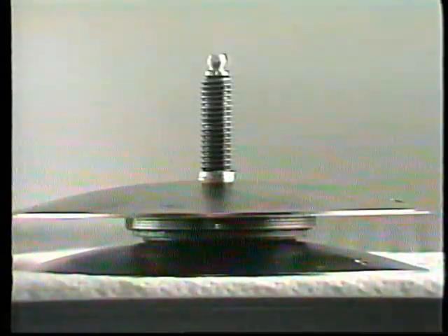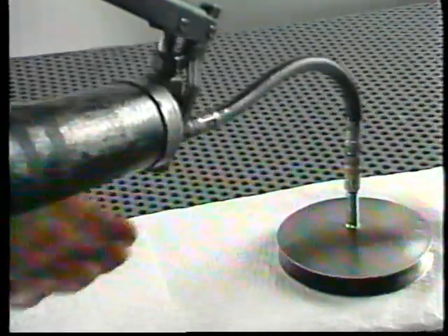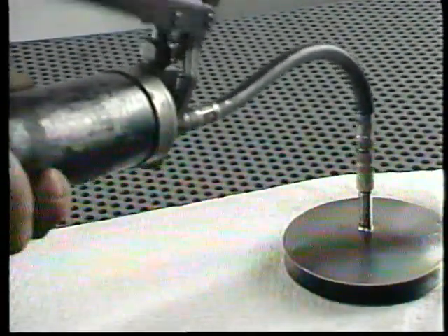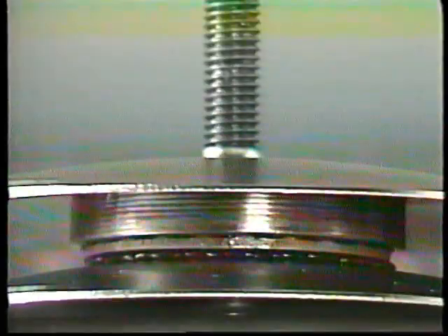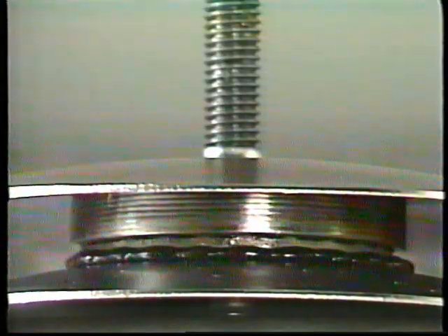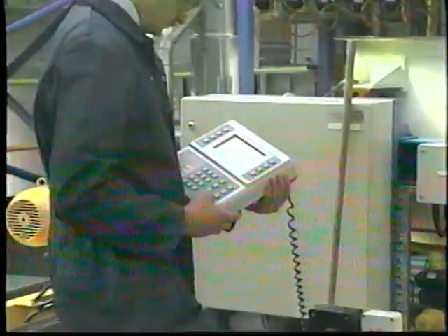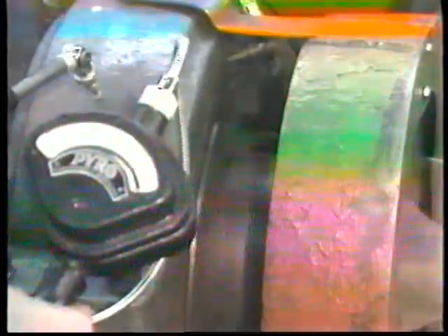If the bearing is filled with new grease, make sure there is some way for any excess to be expelled during operation. Excess grease may make a bearing run hot and could blow out the seals. After installation, it's always good practice to monitor the operation of a bearing when it is put back into regular service. When the machinery is started up, listen carefully to the bearing.